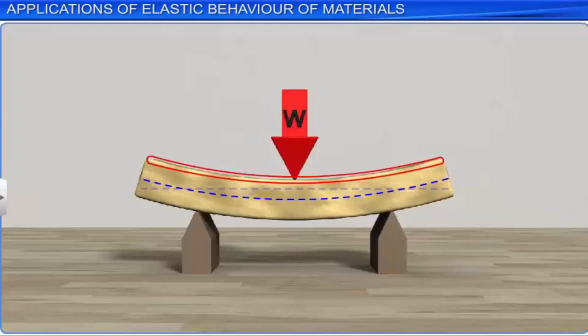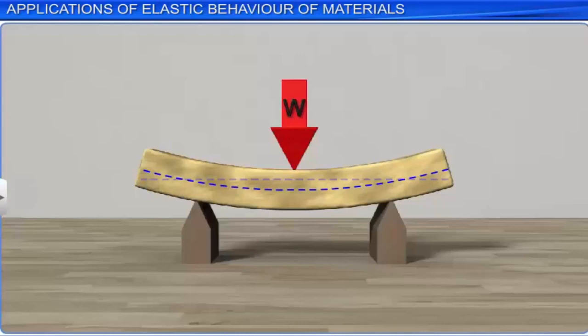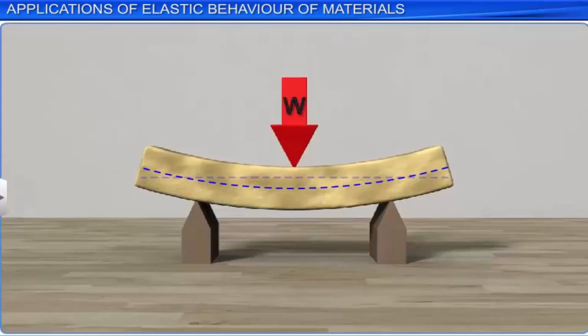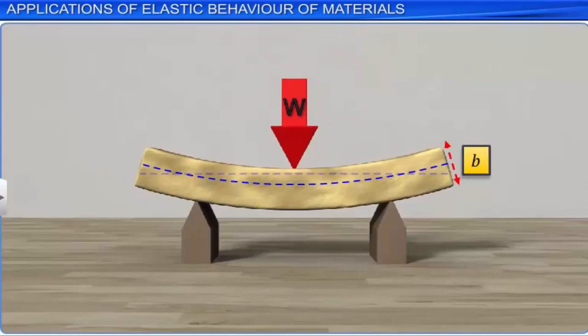The beam will sag or deflect due to the load. The deflection of the beam at the midpoint is its vertical deflection compared to its unstretched position. The greater the width B of the beam, the greater the maximum load the beam can support. The deflection delta at the midpoint can be determined experimentally as well as theoretically calculated.